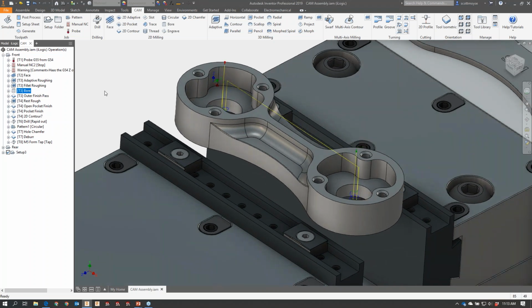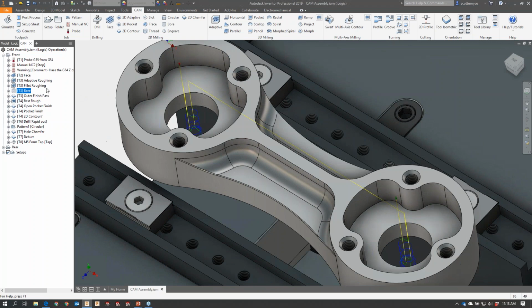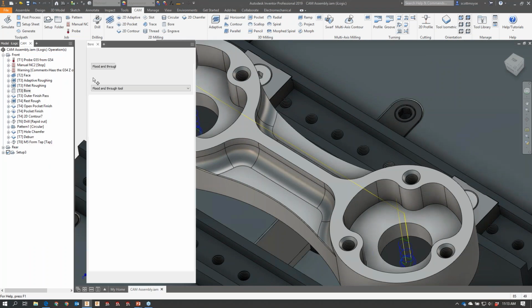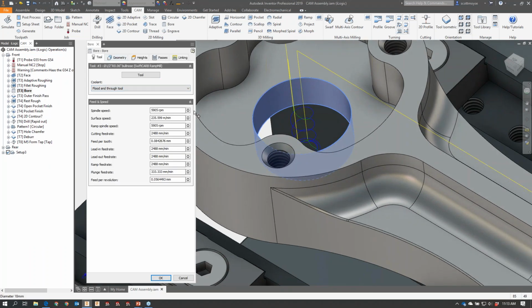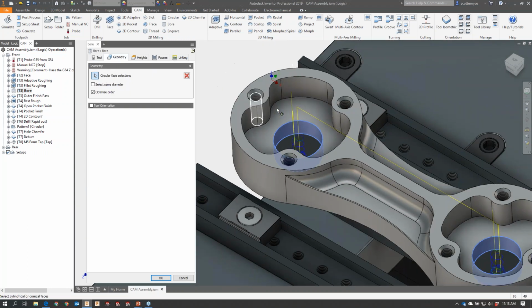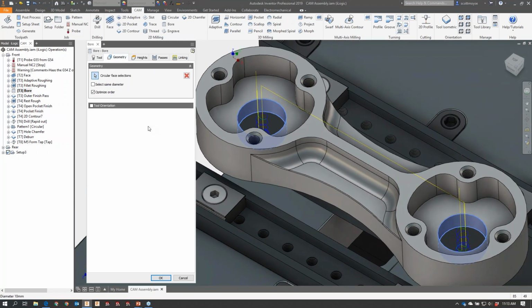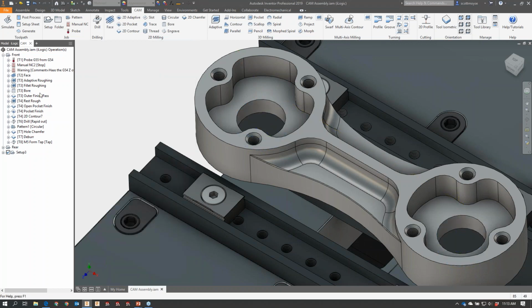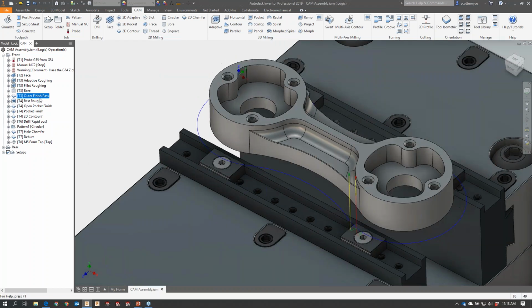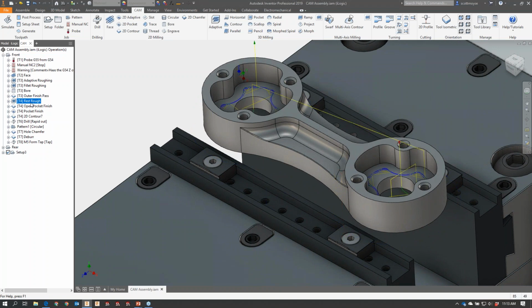I've used the bore toolpath, which is just a simple 2D toolpath, which results in a 3D output. It's just a simple face selection. So very similar to how I showed you to use the hole tool, the drill toolpath. I'm using 2D contour to finish around the outside.